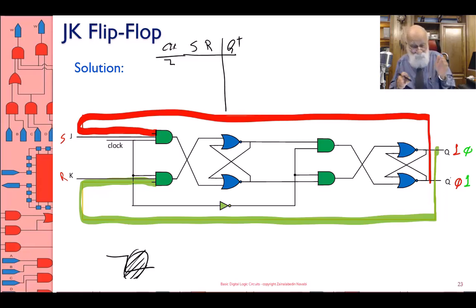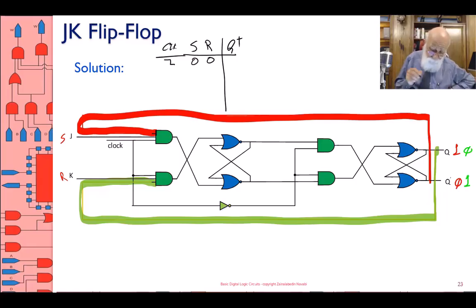After the falling edge of the clock, the output changes. So I'm using this symbol of the clock. The set input, if it is 0, 0, clock arrives, that's no problem at all, because Q plus doesn't change and is Q. After the edge of the clock, if set is 0, reset is 1, again, that's no problem.